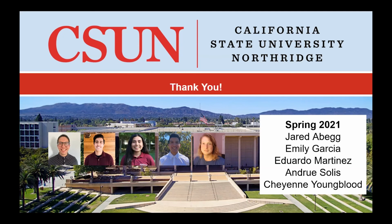I can answer that. I think the flow demands would definitely change if it was a residential system, because we designed it based on the fact that these are office or school type buildings. So the flow demand estimation would definitely change. And I think a lot of us were kind of struggling with figuring out what the size of the pipings needed to be and stuff. There's not a lot of information available on water mains. So definitely maybe could go down a little bit. I think we kind of went overkill with the 10-inch pipe, but yeah, I don't know if CSUN's planning on implementing anything like this. Hope so.